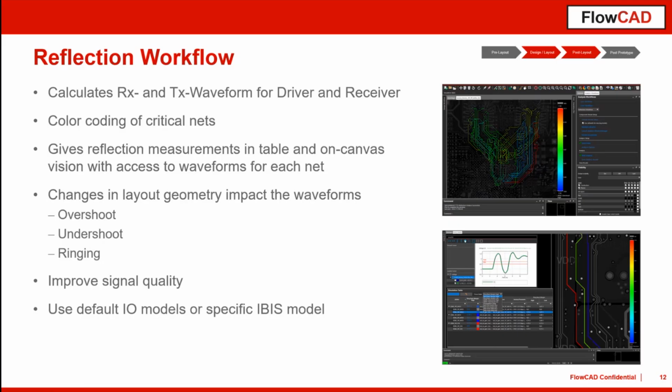In this case, we have to attach IBIS transceivers that enable us to do real transient analysis. A couple of IBIS transmitters come with the installation, so you can choose between, I think, 3 different types that cover the 3.3, 2.5, and 1.2 volt technologies, and of course different rise and fall times and different data patterns can be assigned.